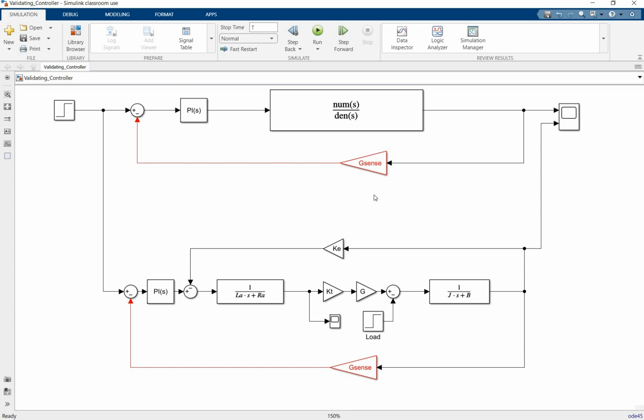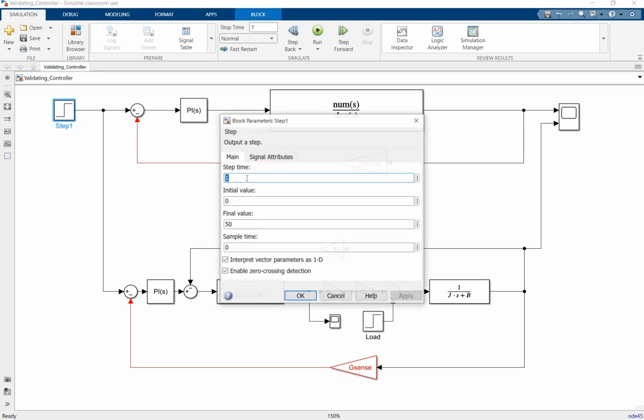And then remember to have your feedback, okay, with the appropriate sensor gain in the system, so that you get the desired response. Okay, so that's the first thing. And then the next element is your input. So to the system input, use something reasonable, because you are setting a speed reference, 100 or 500 or 1000, even though it's going to work at any value.